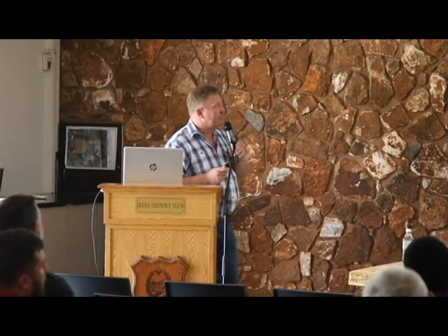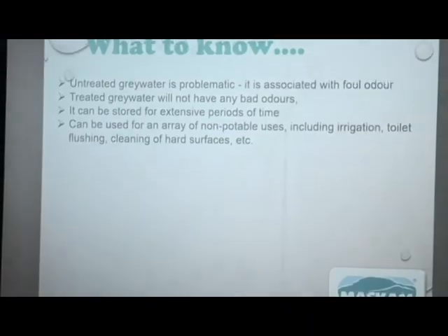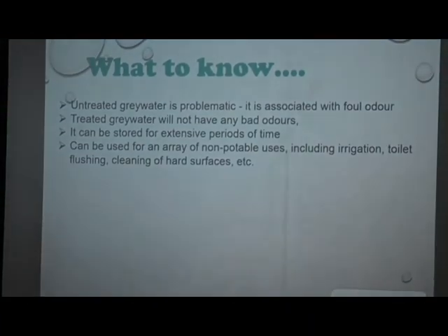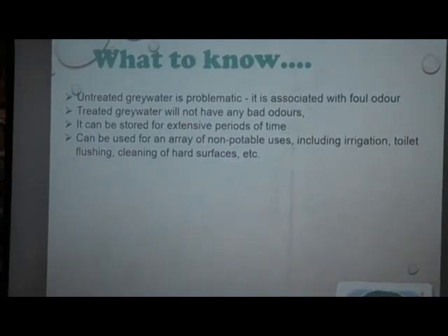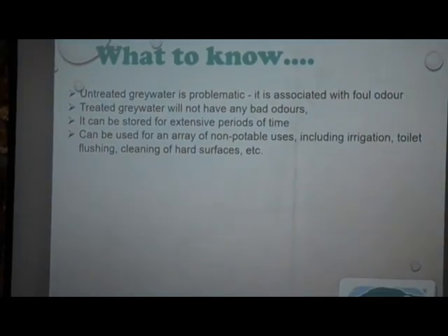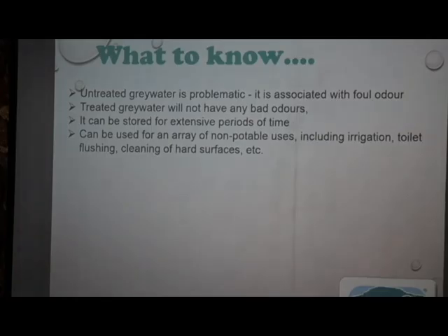But when you treat it, you don't have the foul odor problem. If you treat it, you can store it for months at a time. I know, I've done it. And it can be used for an array of non-drinking purposes. There are guys that put it through filters, taking it to drinking water, but then you need to register as a water services provider. It becomes a lot more difficult. Use it for irrigating your garden, use it for flushing your toilet, use it for hosing off your paving. And then you don't trigger any of those, and it's cheap.